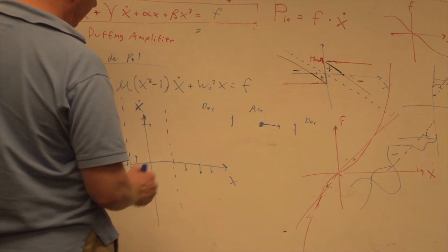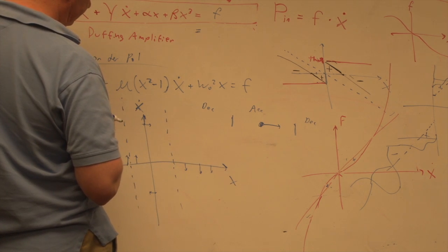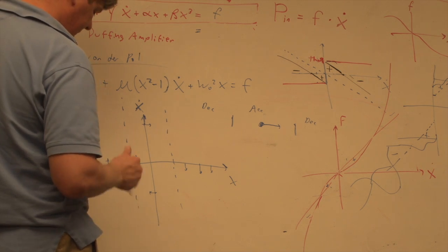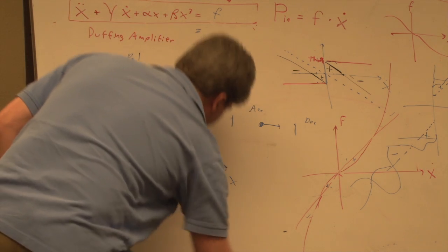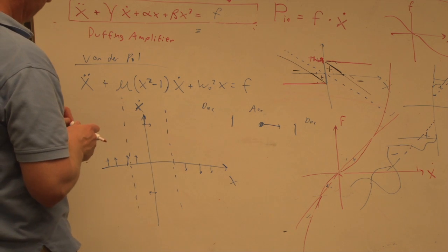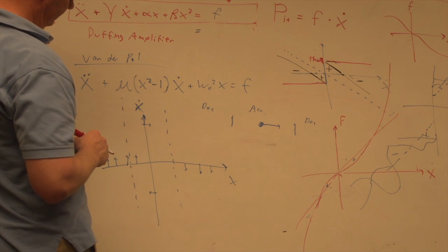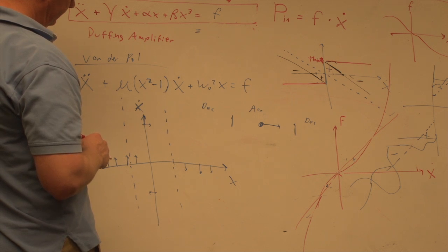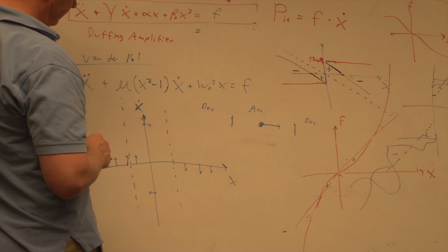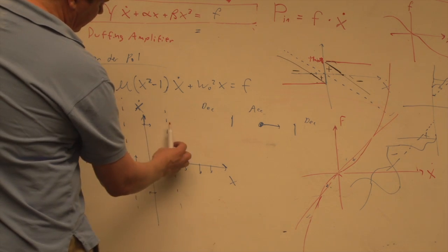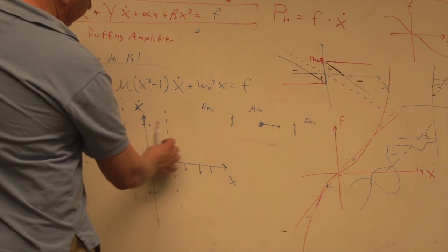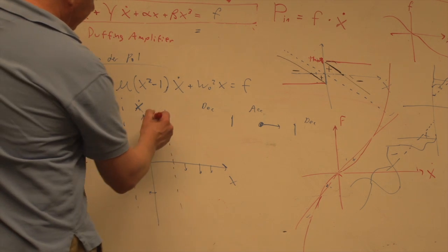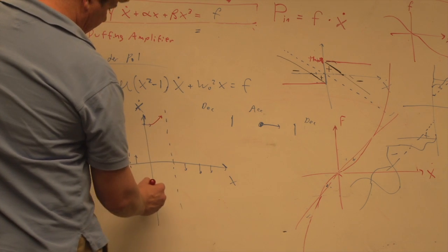I'd like to call attention to the upper right and the lower left diagonal corners, because that's where we're adding energy. If you were to draw an ellipse connecting the mid-segments of the box, the vector would have to be pointed outside the ellipse on those corners, and that's why the phase plot gets those ears on the corners. Because we're adding energy on the diagonals, on the right, lower left diagonal. Well, you're adding energy anywhere between here and here. Right. So it's going to tend to climb in amplitude there. Oh, I see what you're saying. So it's kind of going to go like that. Yeah. Right, and it's going to go like that.